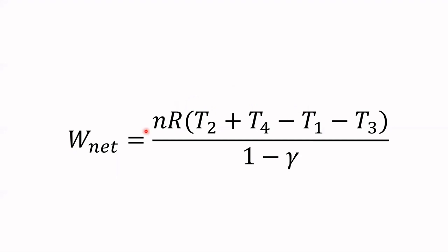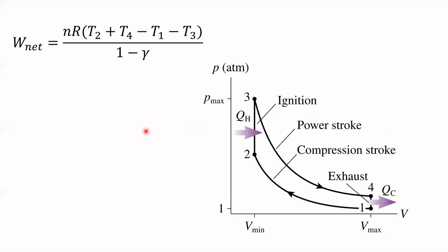Now, again, this is going to be the work done by one cylinder over one cycle. But what we can do is multiply that by 4 to get the work done during one cycle for a 4-cylinder engine, and then multiply that by how many cycles are gone through per second. Normally they state it in RPM, but we can convert that into cycles per second, and we'll have the output power in SI units for an engine, and we can compare that to actual values for common vehicles. Okay, so let's talk about these various temperatures.